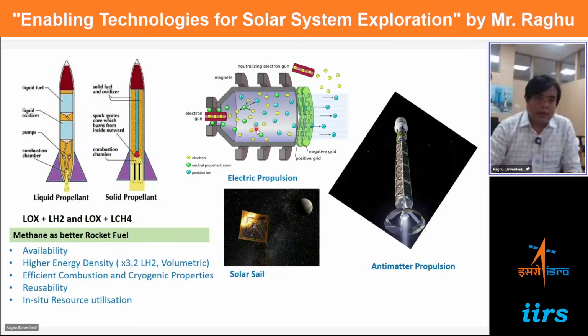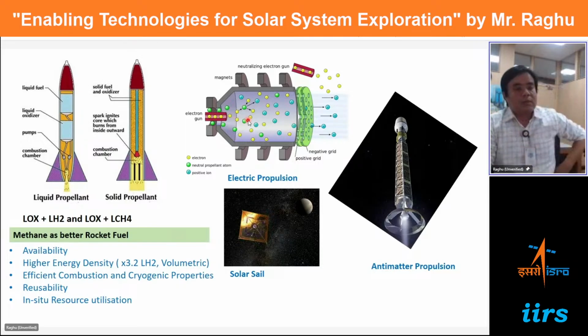Okay, so this is an area where you can work and think about how to improve, because there are different variants. And why xenon is used, and then either krypton or argon, is because here you need energy to ionize the neutral atoms of the propellant. Here the ionization potential is less for xenon than krypton and argon. Because of that it has less power consumption, so xenon is commonly used. But in the SpaceX program, krypton is more commonly used because of the commercial benefits.